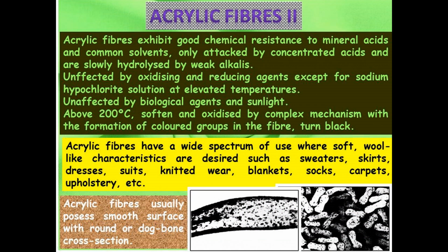Acrylic fibers exhibit good chemical resistance to mineral acids and common solvents, only attacked by concentrated acids, and are slowly hydrolyzed by weak alkalis, unaffected by oxidizing and reducing agents except for sodium hypochlorite solution at elevated temperature. It is unaffected by biological agent and sunlight. Above 200 degrees centigrade, acrylic fibers soften and are oxidized by a complex mechanism. With the formation of colored groups in the fiber, it turns black.